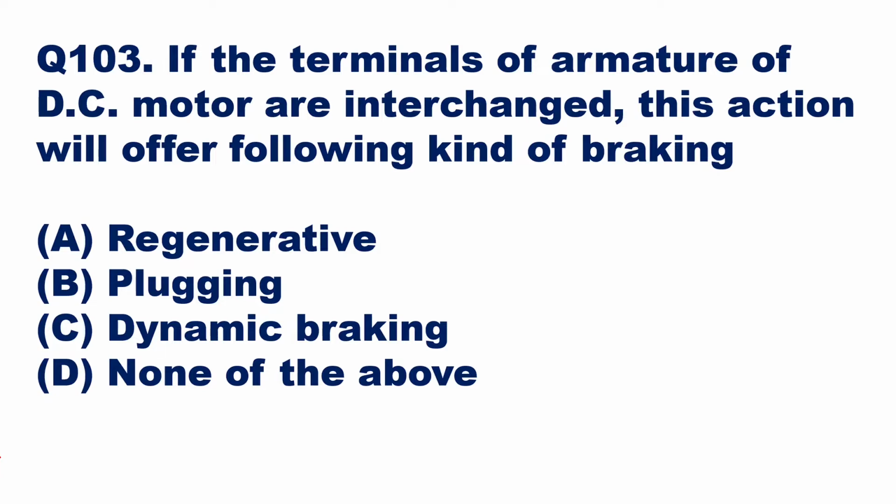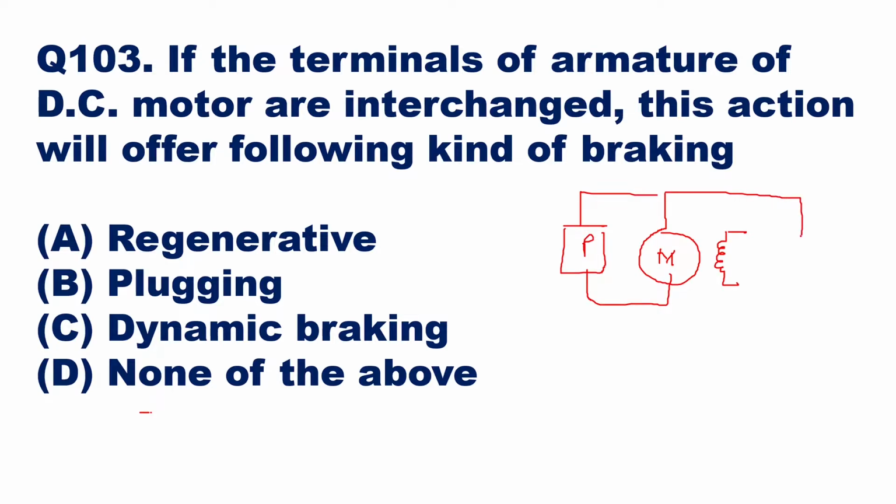So here, when we studied speed control of DC motor, we had a motor here. This is the motor, this is the armature winding, and you can show a field winding here. Now this will be connected by a converter on one side, which will be called the P converter, and it will be connected by a converter on the other side, which will be called the N converter. The P converter is going to convert AC to DC, and the N converter also is going to convert AC to DC.